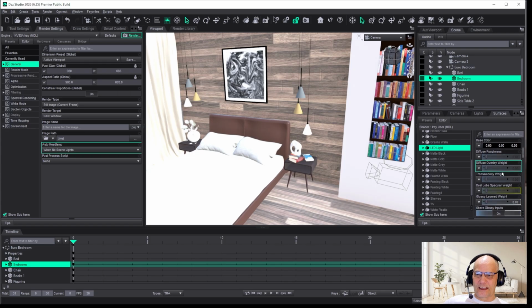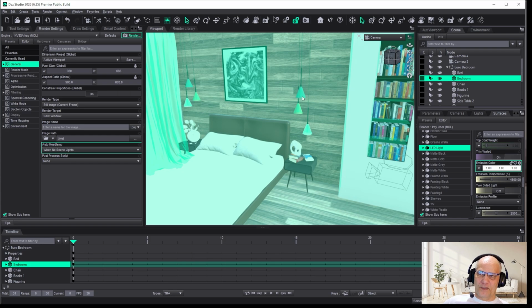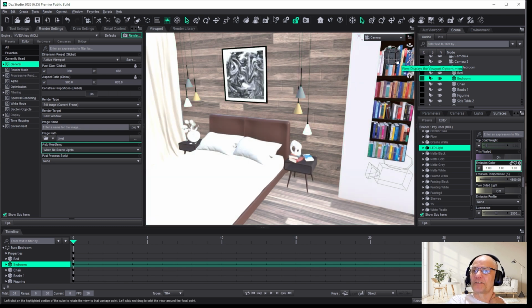And you'll see if we scroll down that there is an emission. Emission value is self-illumination. So rather than choosing a light, you choose emission, and then you turn the emission up and give it normal light properties. And what happens, that's good for putting on a bulb, and then the bulb shines out of here. Not quite as good as a spotlight, but it has different circumstances.